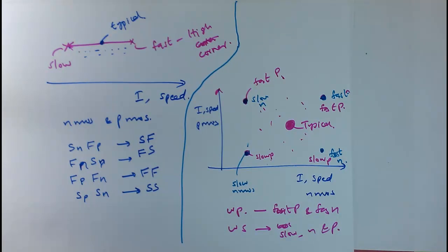So we discussed the process corner variation in resistor and MOSFET, but this is applicable to capacitance and bipolar transistors too, and the foundry which is making the IC will specify all these models. They will provide you a typical model, the fast corner model, and the slow corner model also.